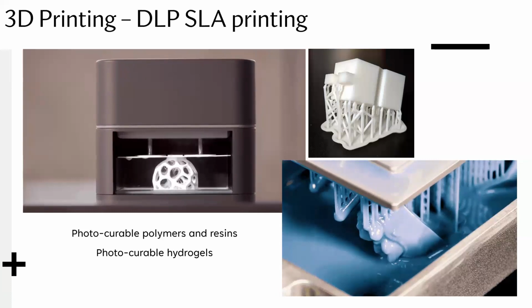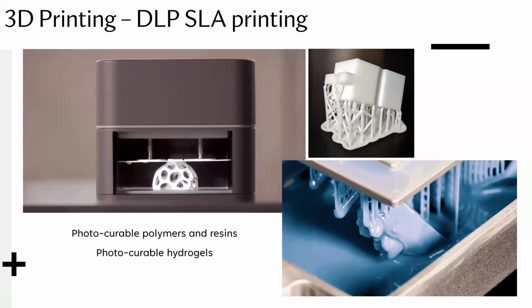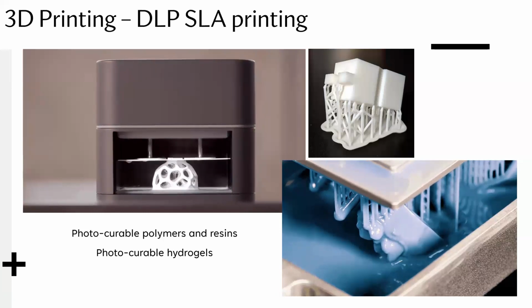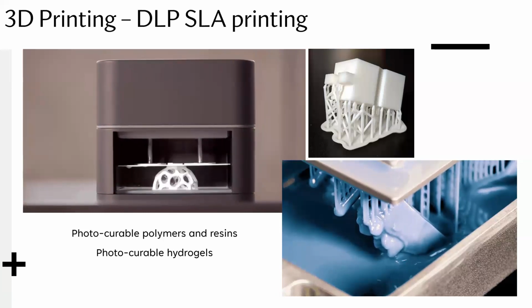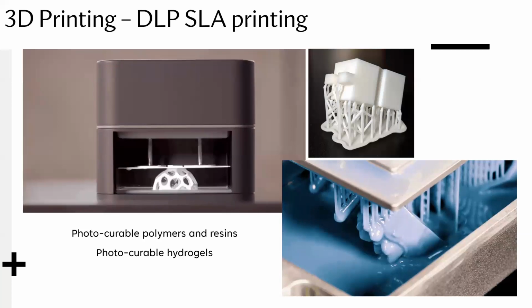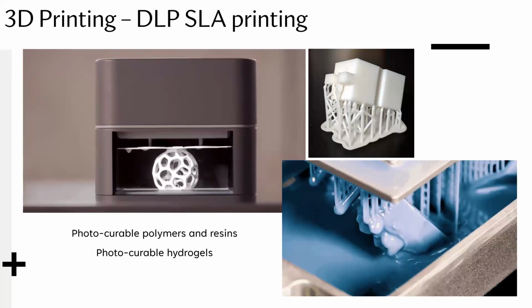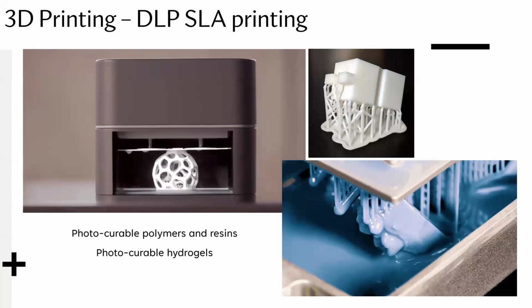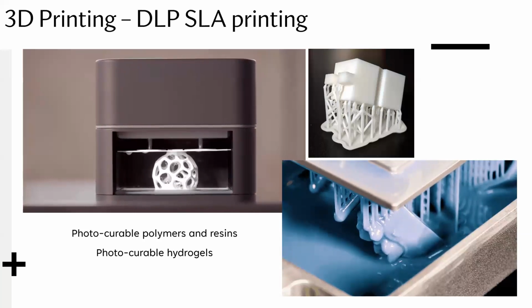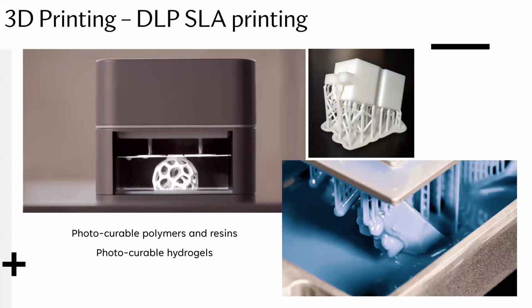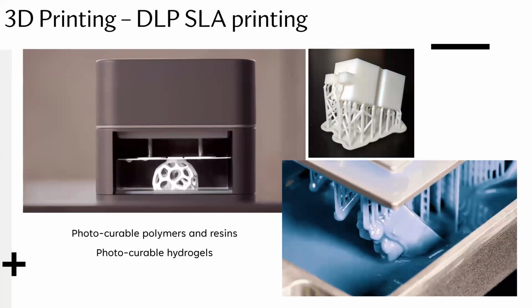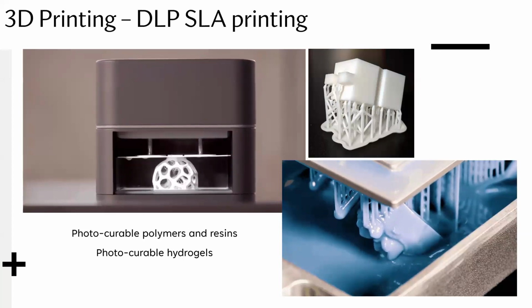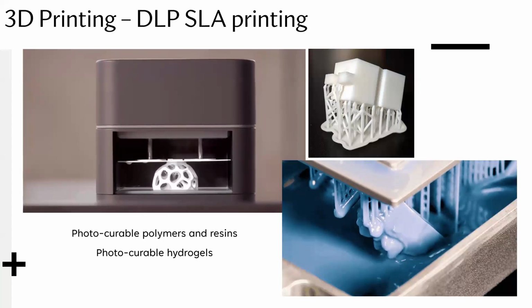Now, another way to avoid that is to have a membrane or a window that is non-adherent to this material. So, let's say this resin was water-based and the window was hydrophobic, it would naturally repel the molecules, and so they wouldn't stick even if they solidified.